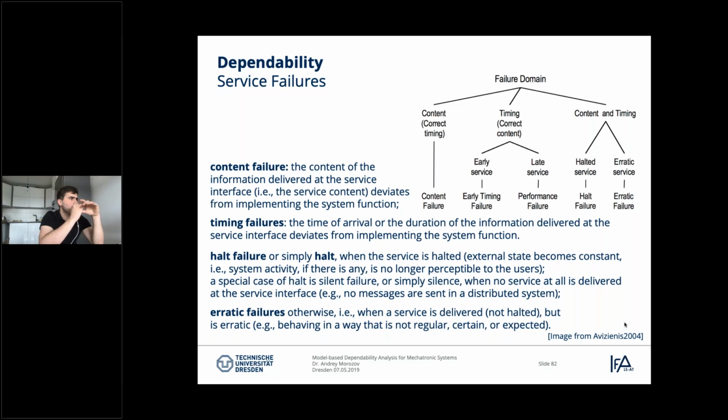And there are more specific things like halt failure, or simply halt. When the service is halted, the external state becomes constant. Let's say we deliver nothing, and sometimes it's called stuck-at fault or stuck-at failure. And then erratic failure: a service is delivered but is erratic, behaving in a way that is not regular, certain, or expected. So halt means we deliver no service, and erratic means we deliver incorrect service and it is differently incorrect over time.